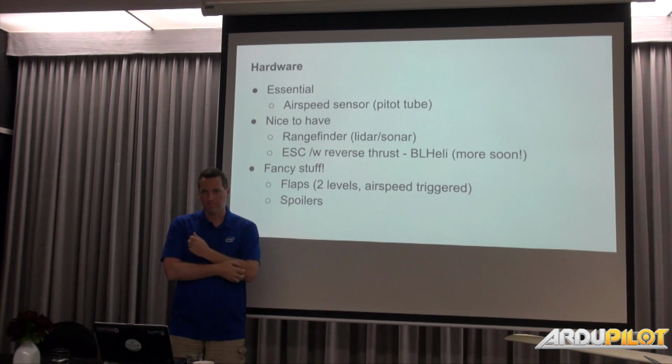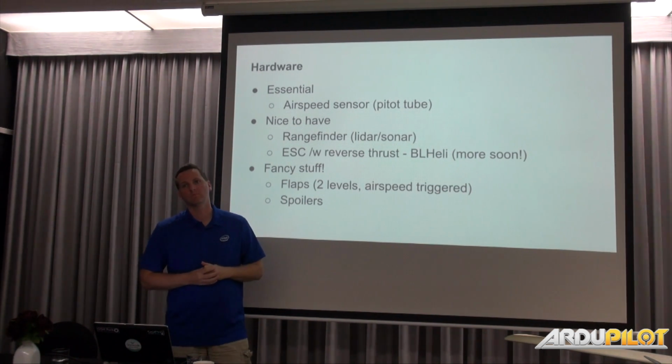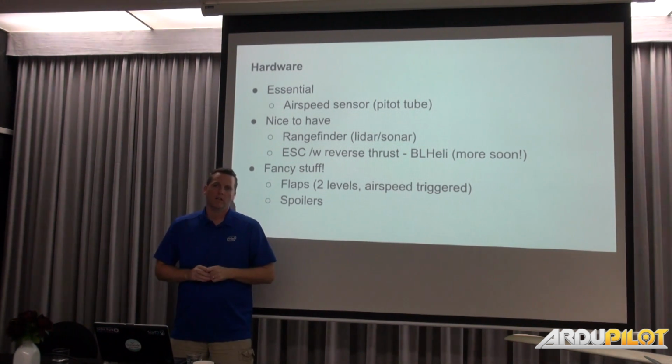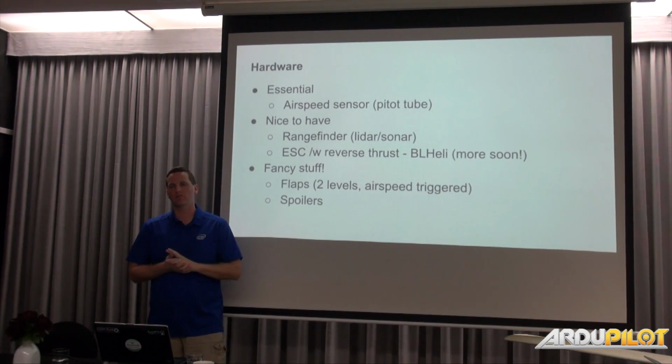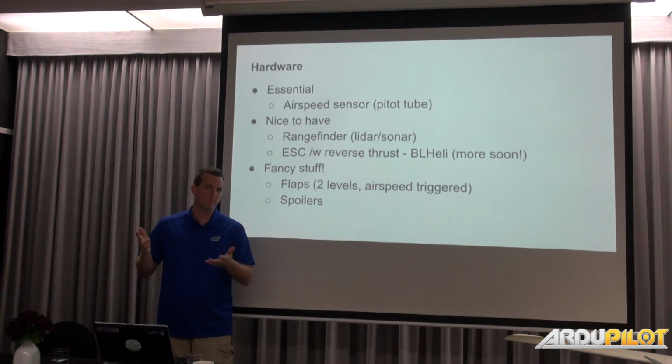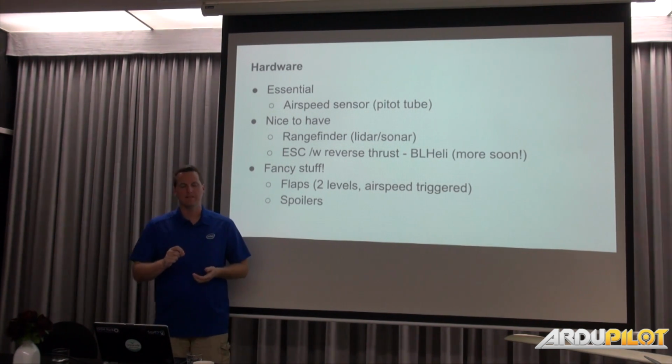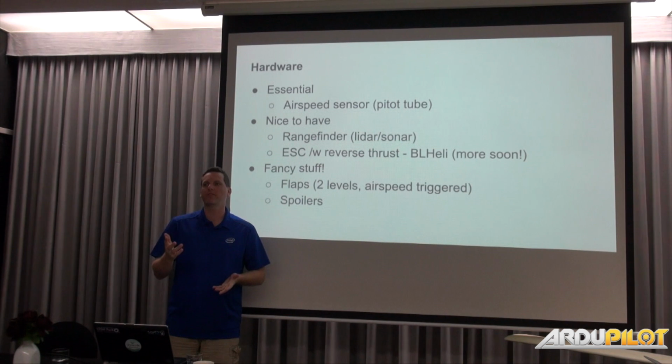So the LiDARs are useful out to 40 meters, but mainstream sonars only work to about 6 meters. Is that too late to help in the landing sequence? Usually, I definitely recommend LiDAR. Sonars are good for flaring, because that's like a 2 meter sort of thing. LiDARs are obviously far superior as rangefinders than the sonar. Even the cheap ones are like a 30 meter sort of thing, unless you have a tiny one, when they're older. So you want LiDAR if you can.